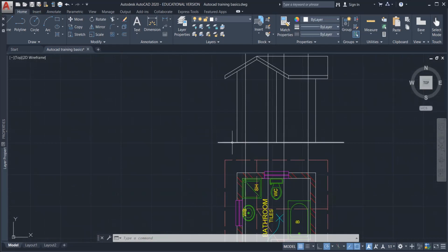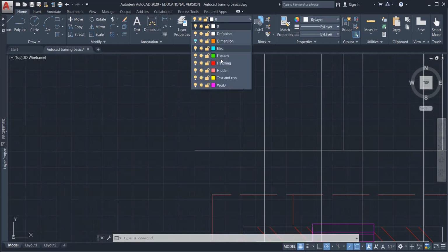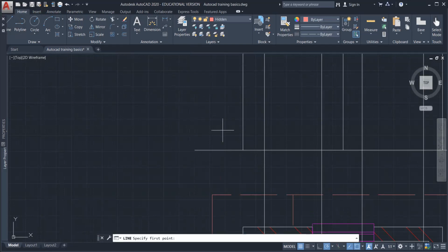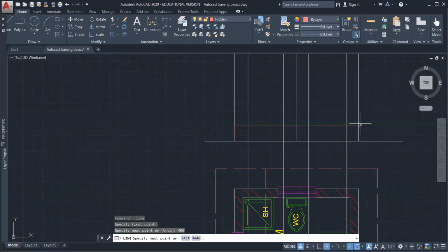Now be careful. The floor is not just built on the ground itself, it's higher up. How far up? This is also given to you. It's usually drawn 400 millimeters above the ground line. So 400, take it up, 400. Okay, take it across all the way.